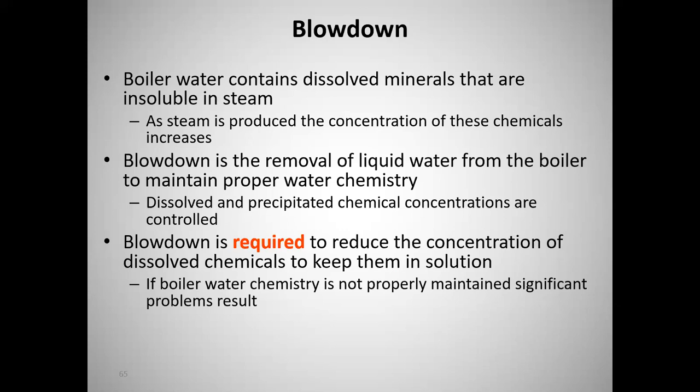So you've got makeup water coming into your system, bringing a steady supply of minerals in, and then it goes into the boiler and we produce steam. Well, very few minerals carry over in steam. So, minerals coming in, pure steam going out, where are the minerals? Well, they stay in the water. And so the concentration is going to continually build and build if we don't do something, until we start scaling up. So blowdown is the solution.